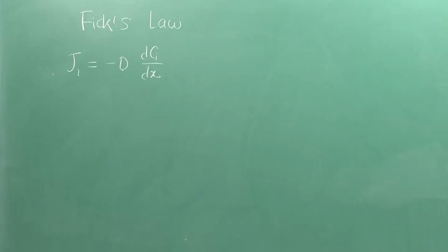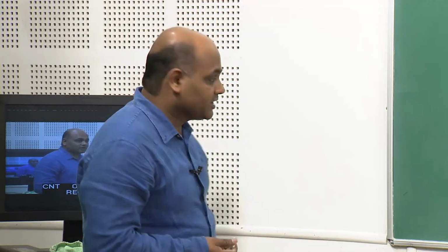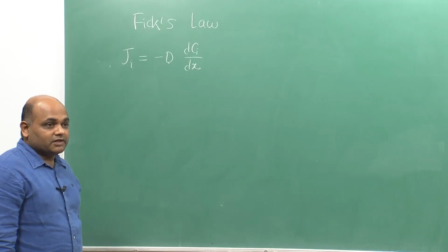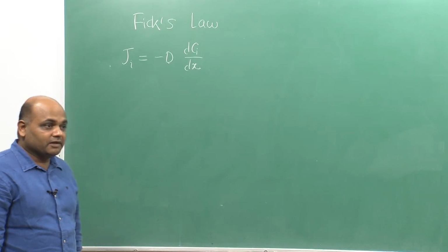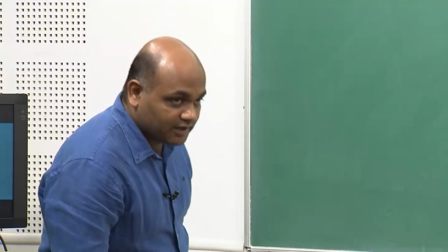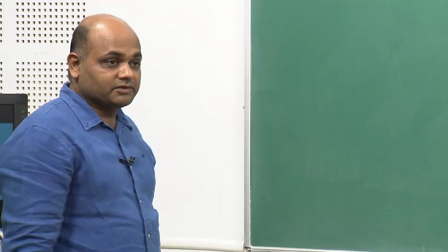So, this flux based upon the concentration gradient of the component is also referred to as Fickian flux. What can be other reasons for getting a flux? If there is an external driving force, you might also get a net velocity of the components, or the net velocity of a concentration plane because of the external driving force, and it will also be added to the flux term.